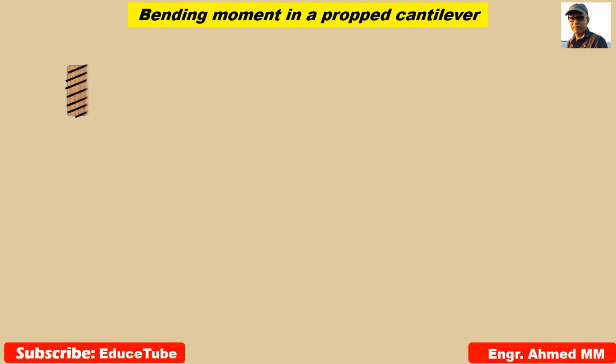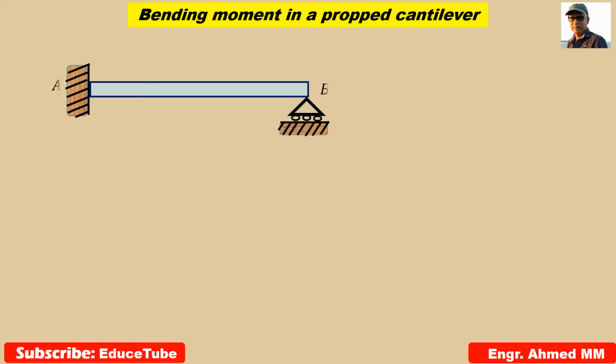Today I am going to show you how to find the shear force and bending moment in a propped cantilever. This is a propped cantilever having a concentrated load P acting at a distance L by 2, so it is at mid-span.